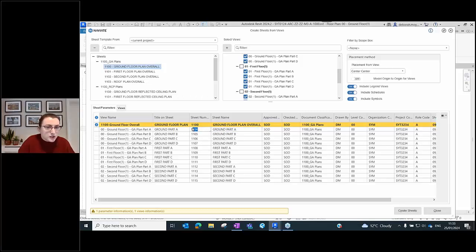I am going to set my sheet numbers as well. I want my series to start at, let's say, 1110. This is smart. It will prompt you if there are any duplicate numbers in there. So I can clear that warning before I go to my next step, which is now using fill increment. So I've used fill increment. These have all increased in value up by 1. I have no duplicates. So all my sheets are numbered, all my sheets are named.